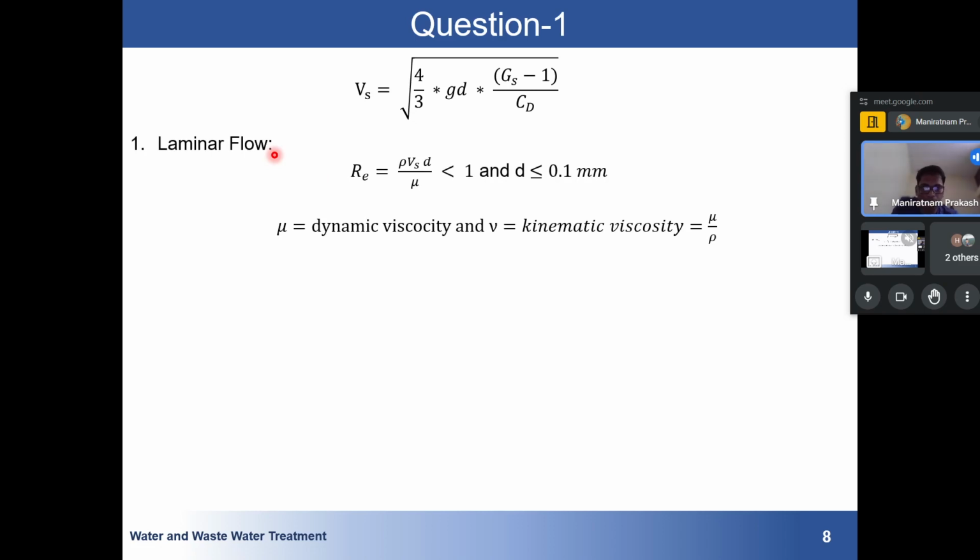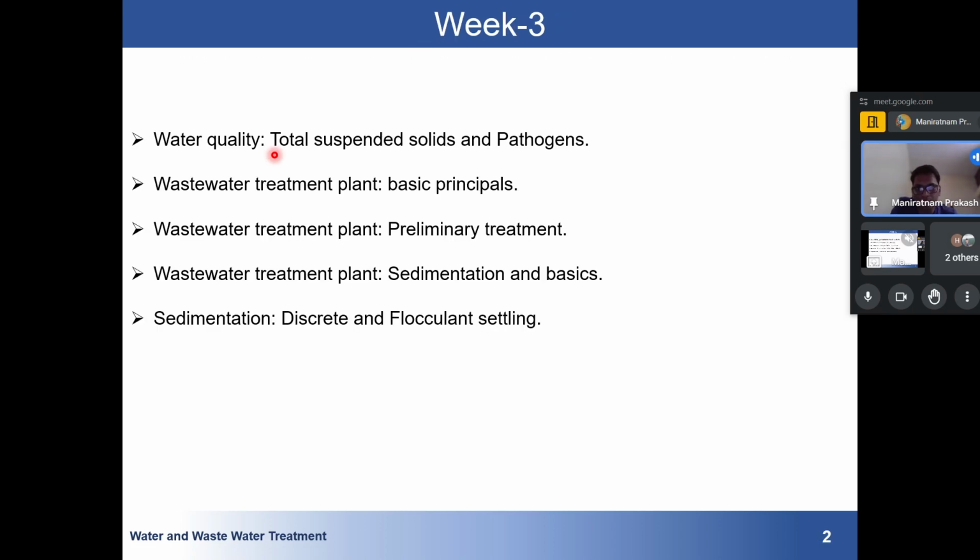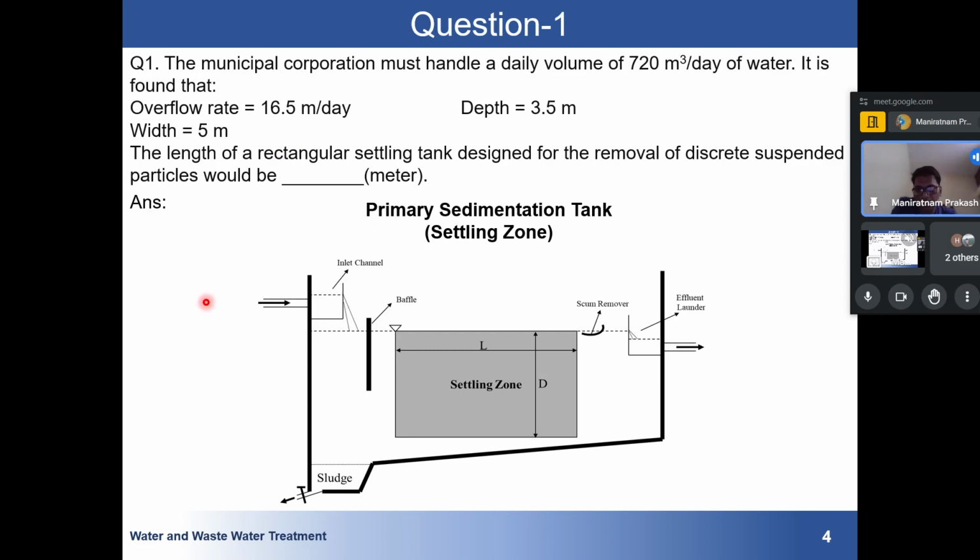I have discussed that when water goes to the settling zone, it first strikes the baffle zone. I will just go through the picture once again. See what will happen: here the water is coming in a very turbulent flow. If I pass it directly into the settling zone, some particles will settle down, some particles will just scatter here and there and might not get settled. So our target is to pass our water very gently into this system.